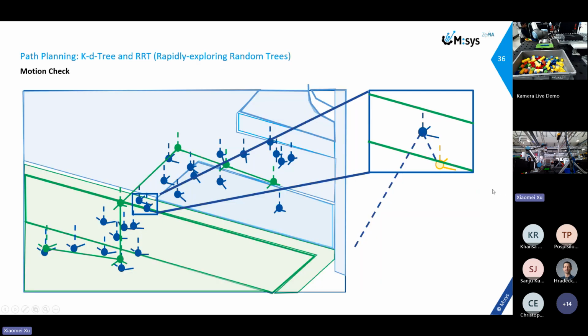The temporary waypoint is valid during motion checks if the 5 intervals don't overlap. The path planning saves it. Starting from this waypoint, the next neighbor is found using the same 4-step process until the waypoint endpoint distance is within the KD tree range. If a collision occurs, the last valid interval point replaces the temporary waypoint, ensuring the path planner proceeds towards the endpoint.